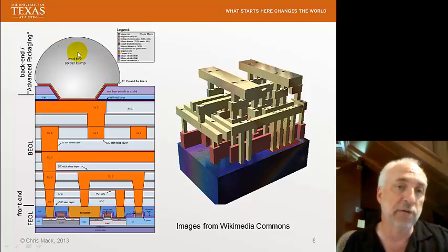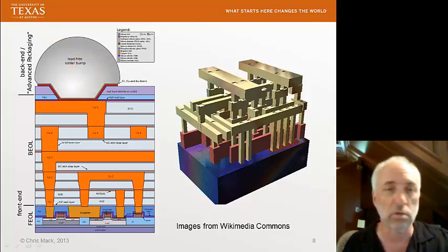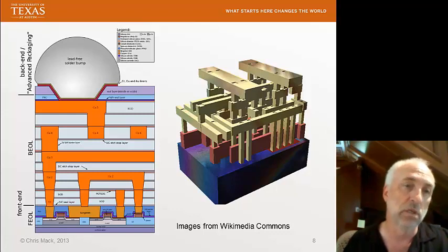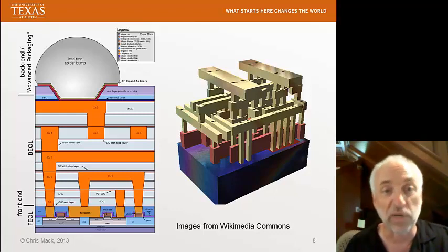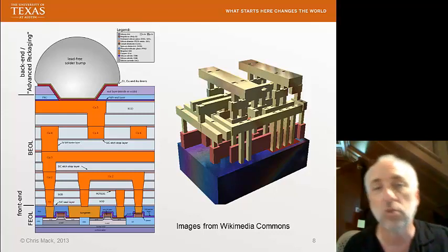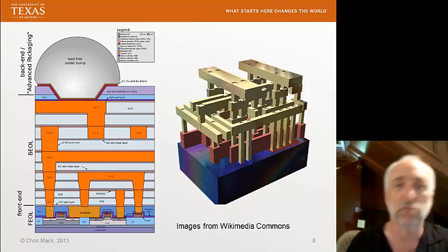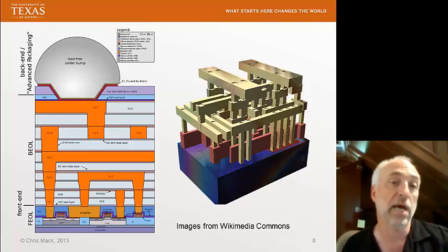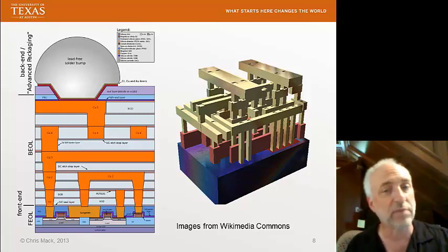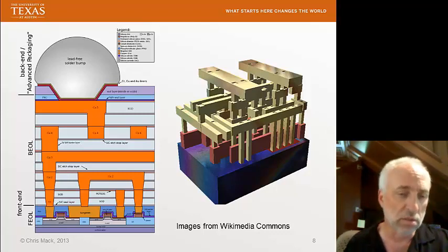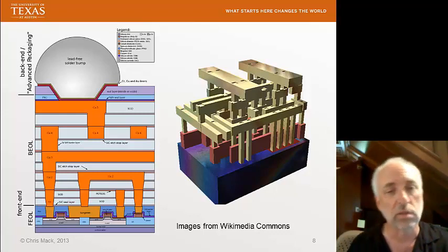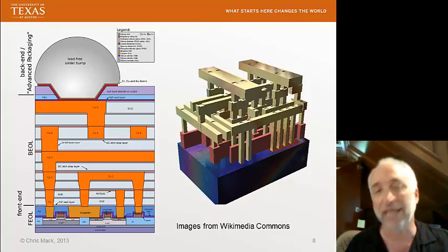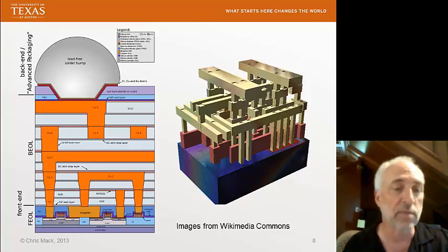And finally at the top we're going to have some connection to the outside world through the packaging. Here it's a solder bump that will then connect to a package which has a lead that comes out and connects to our world. Well, you can see that there's a lot of metal layers. This is just 5, and we have up to 10 today. It occupies a lot of the portion of the chip making process. In fact, we do more lithography steps and more deposition steps in the back end of the line in many processes today than we do in the front end of the line.